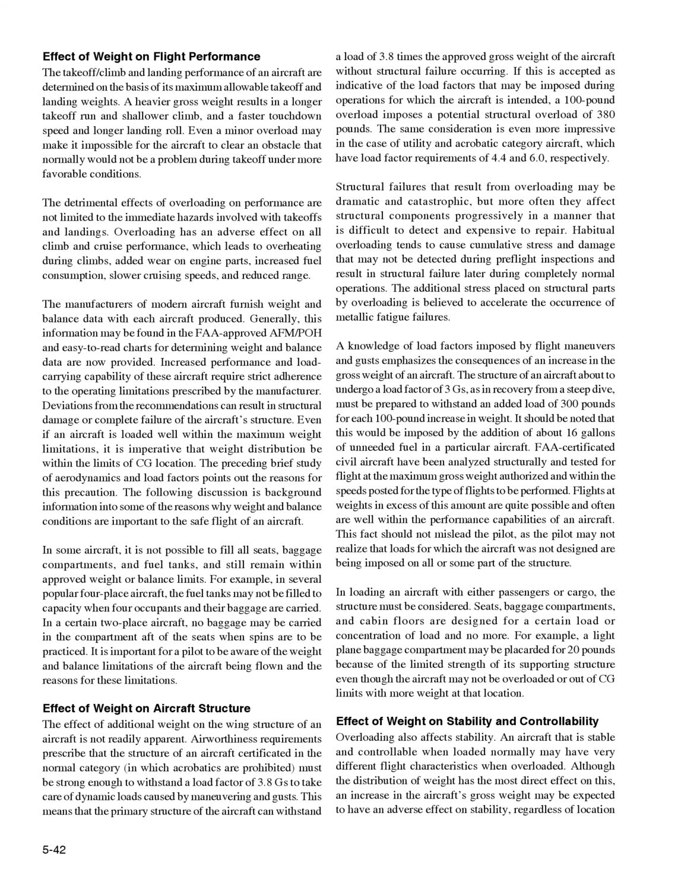FAA certificated civil aircraft have been analyzed structurally and tested for flight at the maximum gross weight authorized, and within the speeds posted for the type of flights to be performed. Flights at weights in excess of this amount are quite possible and often are well within the performance capabilities of an aircraft. This fact should not mislead the pilot, as the pilot may not realize that loads for which the aircraft was not designed are being imposed on all or some part of the structure.